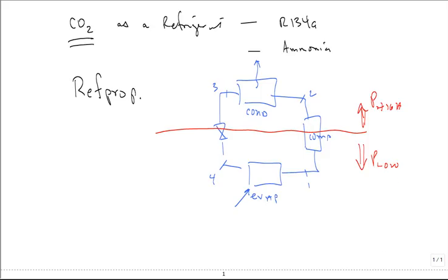If you want to make ice, you probably want the fluid to be coming out, let's say around 0 degrees F, such that there's maybe a delta T in the evaporator of about 15 degrees F, meaning that it can keep something cold at around 15 degrees F, okay? You would be passing maybe air over this evaporator coil, and that air would be coming out at around 15 degrees F, 15 degrees higher than 0 degrees F. Maybe it would pass through the room that you're freezing the product in, and maybe it would pick up another 10 or 15 degrees and come back.